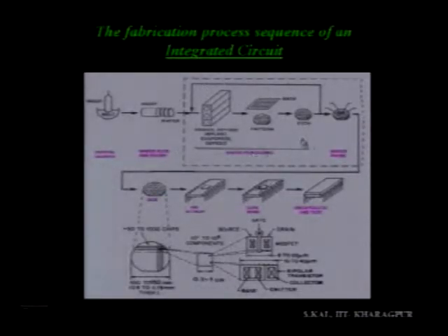ready for processing. And in this processing, the one part you can see here which is a furnace or some implantation equipment is used here. So that is for oxidation, making silicon dioxide, for diffusion of impurity atoms, for getting diffuse layer. Then comes implant, it is also for incorporation of impurity atoms. Then evaporation, deposition of metal films or some other semiconducting films also you can make here. So this is this step.